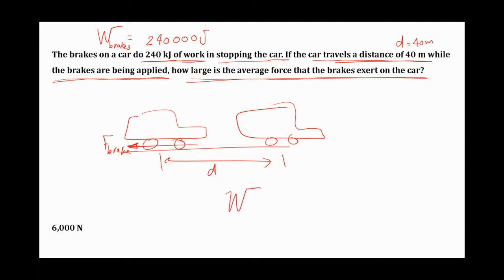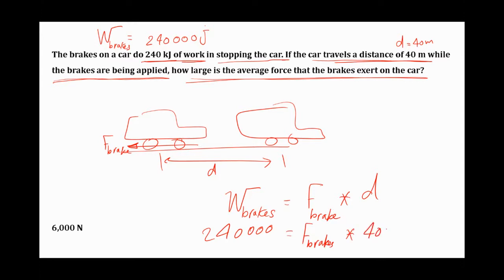So the work done by the brakes equals the force of the brake times the distance. So 240,000 equals the force of the brake, which he's asking about, times the distance 40 meter. So the force of the brake equals 6,000 Newton.